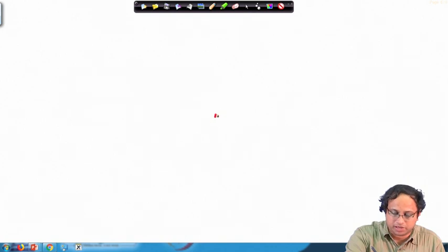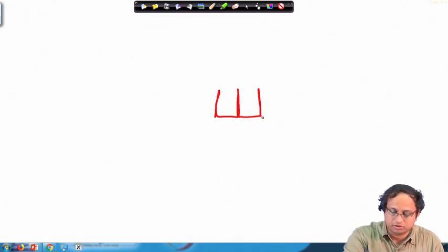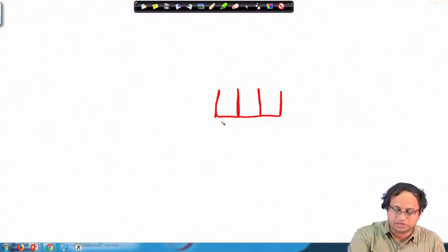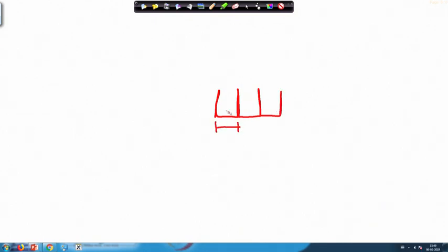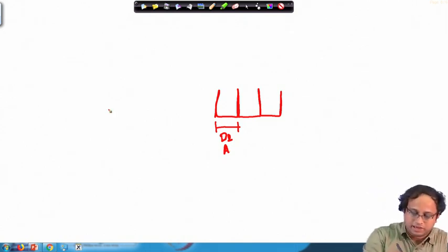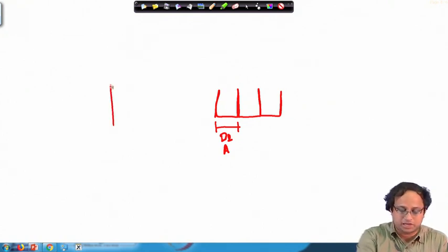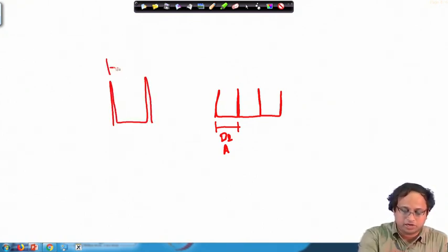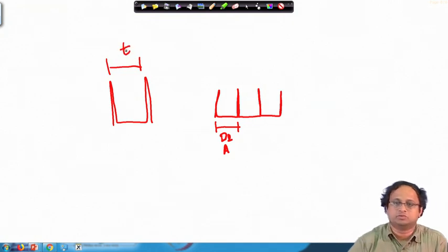Suppose these are your spikes in the power trace. They comprise the instance between doubling and addition, that is, you are doing both double and addition. For double you have 4 clock cycles, whereas for addition you have 8 clock cycles. Now imagine that you observe two spikes and record the time t between these two spikes.